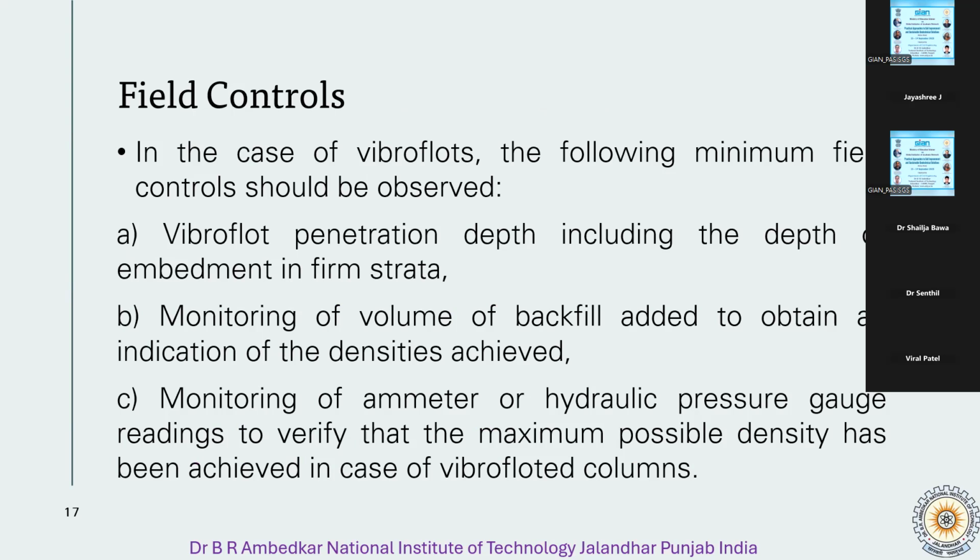Again, we have to always apply some field controls. Especially when we are going to use the vibro floats, we have to keep in mind the penetration depth, including the depth of embankment in the first strata, monitoring of the volume of backfill added to obtain an indication of the densities achieved, and monitoring of the ammeter or hydraulic pressure gauge readings to verify the maximum possible density that has been achieved in the case of the bottom feed columns.